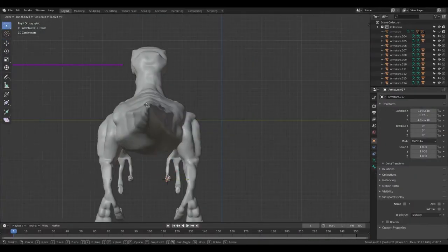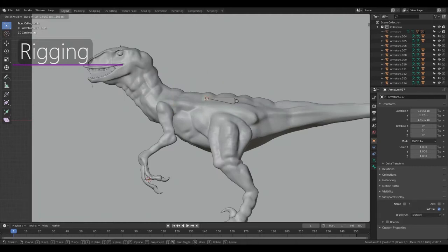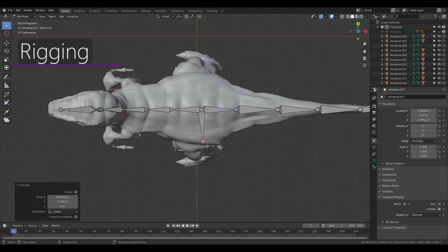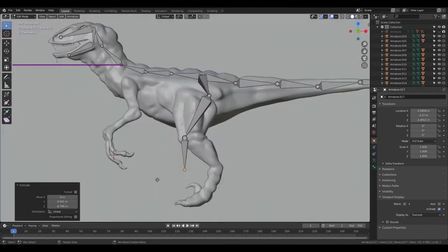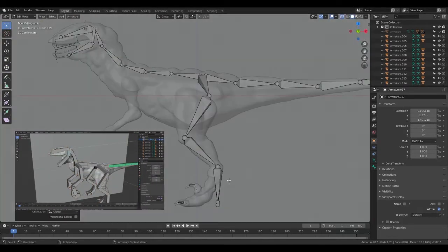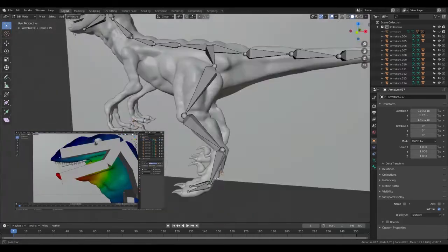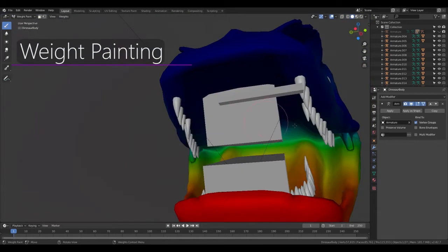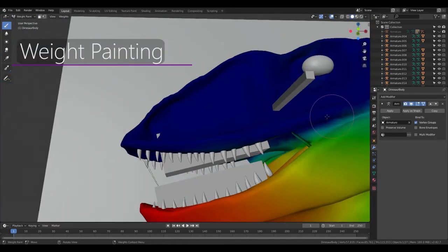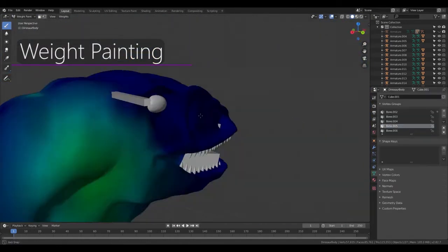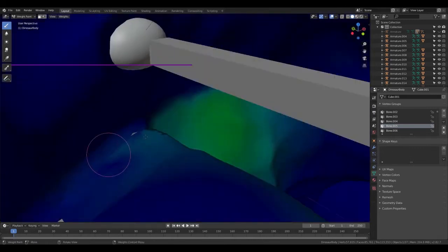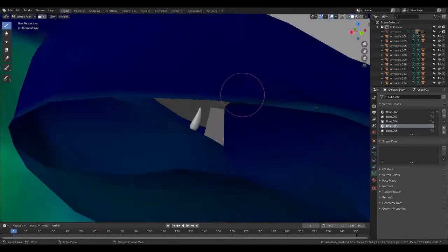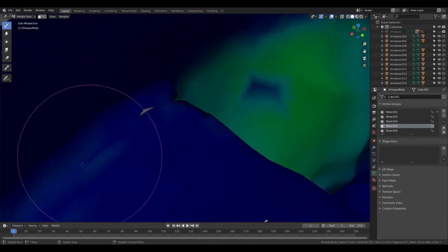Another crucial part of the creature was the bone structure, which would be used for animation. Using Blender's armature object, a quadruped-style bone structure was created. Extra bones were also created for the teeth, nails, and eyes, which could be linked to the main skeleton. The bones were then linked to the mesh with automatic weights, meaning that they would be assigned automatically to the limbs of the mesh. This required some weight painting, or skinning, to separate the polygons from certain bones.